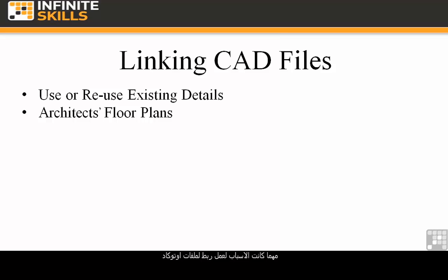Whatever the reason for linking CAD files, you may actually want to do a tidy up before you link them into your precious REVIT model, because let's face it, with all the best intentions in the world, sometimes the architect's 2D CAD file isn't the tidiest of things that he sends you. So in this exercise, I want to explore some of the prerequisites before we link that CAD file. I want to clean up the architect's floor plan before it gets anywhere near my project.